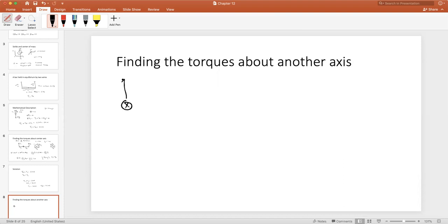So remember, this is where our left tension was. The bar, which is 2 meters in length, at the center of mass, there is still going to be mg, the mass of the bar times g, and at the very end, this will be T_R. So this distance here is 1 meter, and this whole distance is 2 meters, okay?